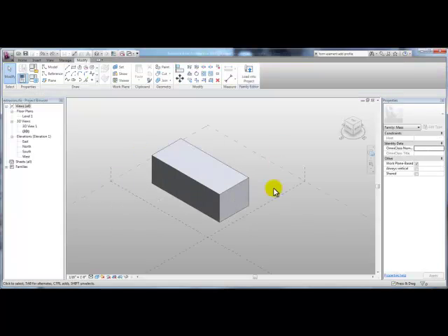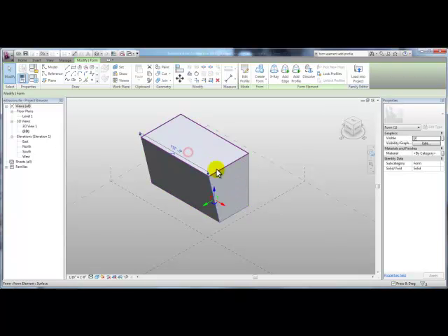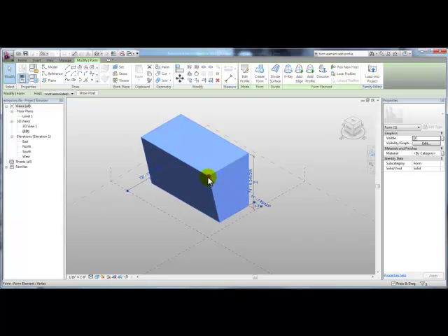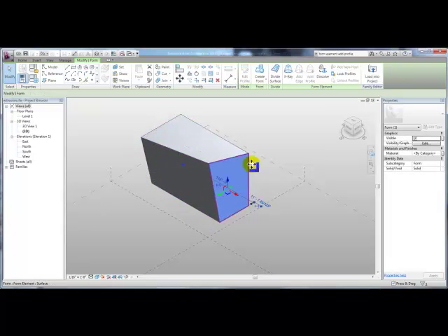You can use these toggles on different faces of the model, or on one of the edges here. Notice that if I use the Tab key, I can tab to the different edges, surfaces, and even the point at this corner here for more control over editing. Select the form and pick X-Ray so that you can see through the geometry, making it easier to add profiles.